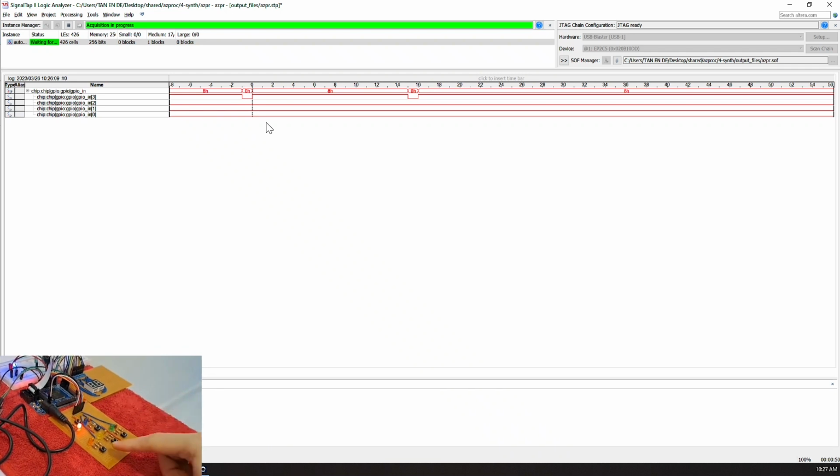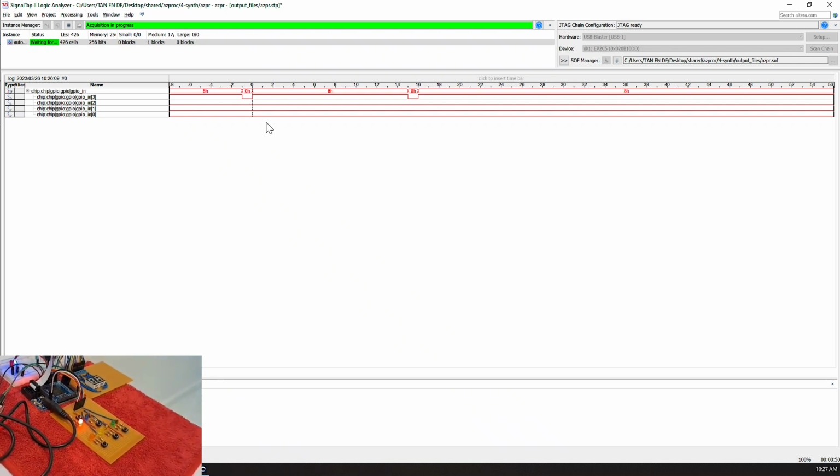And I've already designed the circuit without the debouncing mechanism. So I have to deal with it because I don't want to modify my hardware input here. I'm running out of time for the next project actually. So I have to use software debouncing.